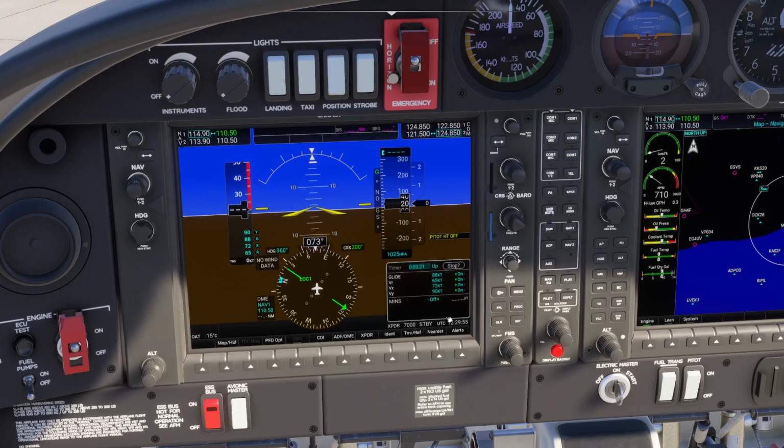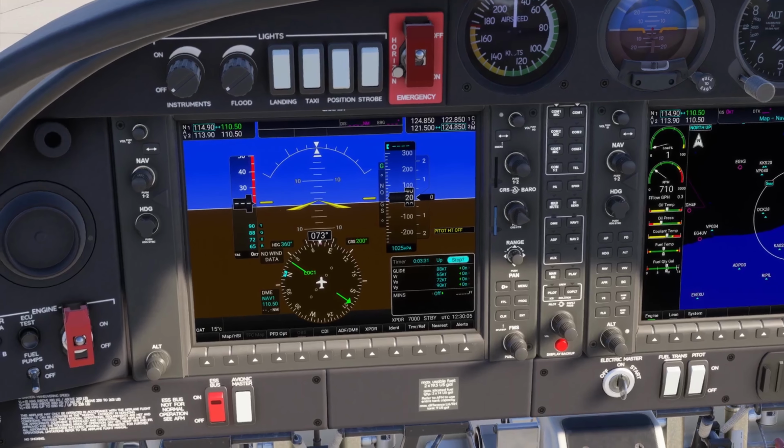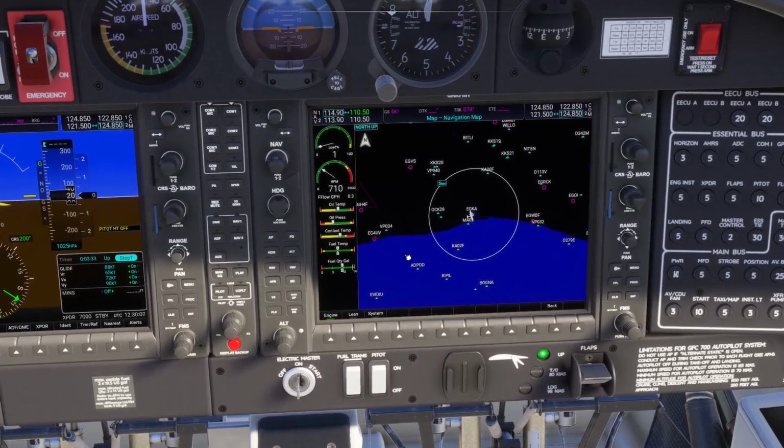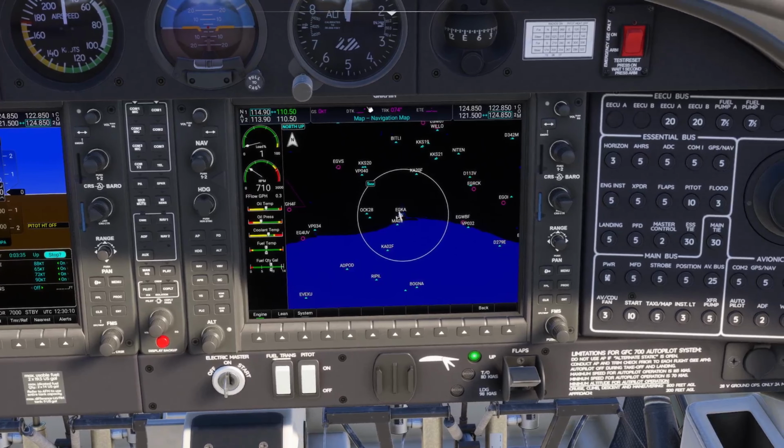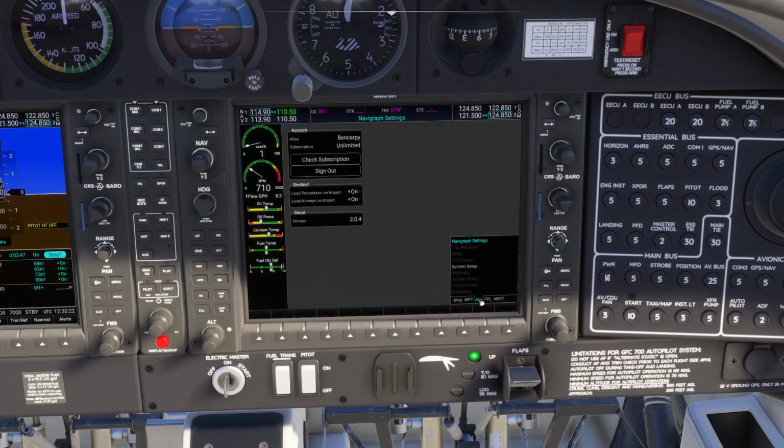Then we can press timer and reference. This is the screen you want to keep up whilst you're flying. So this will tell you your speeds as well as the timer. Then when you come across, you want to check the MFD. So you want to check your fuel is in balance. And you also want to check the fuel down there is correct, which it is. And then you rotate the FMS to aux.